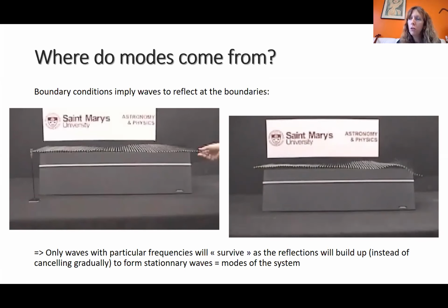And so when you measure your free plates of the violin, if you actually use different conditions, like for example, George Stoppani has designed this new device to actually make pinned edge conditions, you will get different mode shapes and different resonance modes. So talking about the resonances of the system, you really need to define this system properly and how are the different boundary conditions and everything, because you change this and of course you will change the modes.